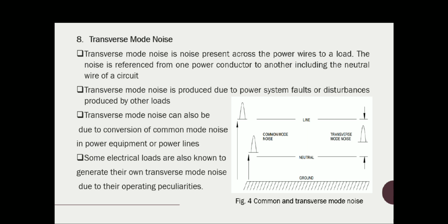Transverse mode noise can also be due to conversion of common mode noise in power equipment or power lines. Some electrical loads are also known to generate their own transverse mode noise due to their operating peculiarities. In this figure, you can see the common mode and the transverse mode noises. The common mode noise is measured in between the line and ground. Transverse mode is measured in between two lines or neutral.